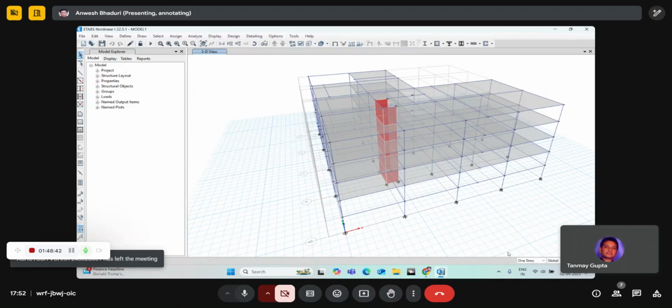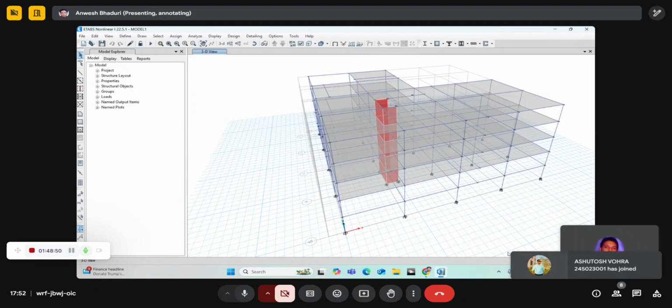Those hinge states are there in the post processing, that you can see. As per the hinge rotations, you will get the results. Perform 3D is specifically devoted to nonlinear analysis. In ETABS it is like an add-on; we do the linear analysis and the designs.